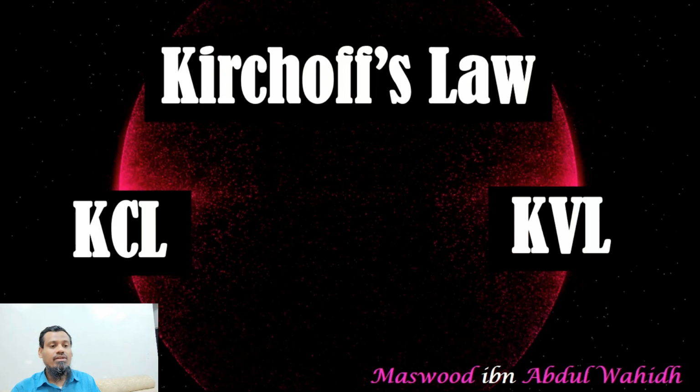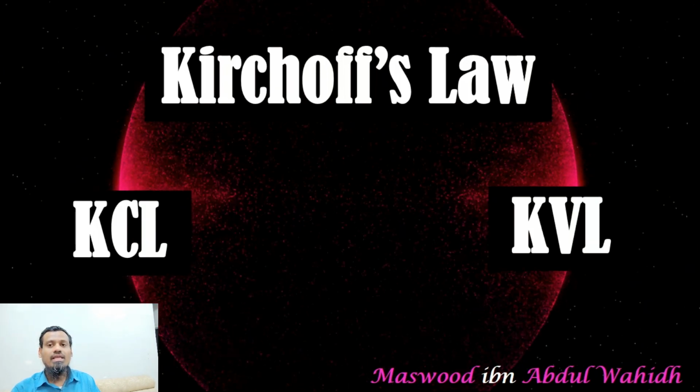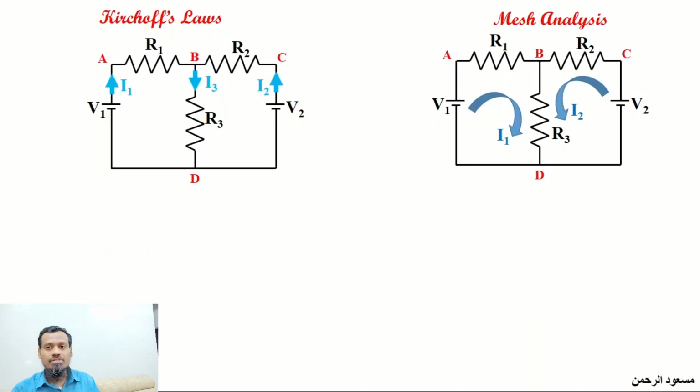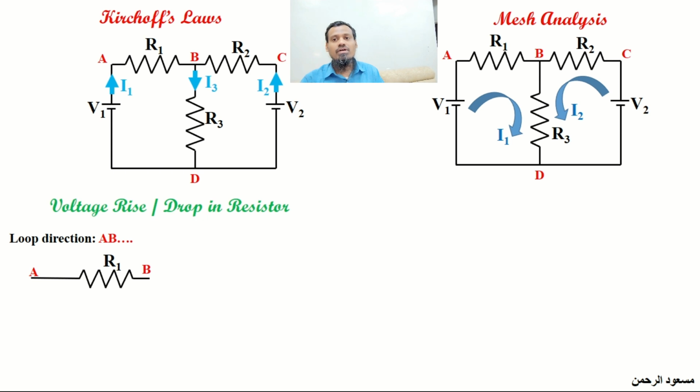And we went into the solution of one problem using KCL and KVL. So we are going to take another problem which is again from a university question paper. Once again we will look into the keynotes for the solution of a problem using Kirchhoff's law or mesh analysis. In both cases we are going to have some loop directions and we are going to assume current directions. In the case of Kirchhoff's law, we will be assuming branch currents, and in the case of mesh analysis, we will be assuming loop currents.